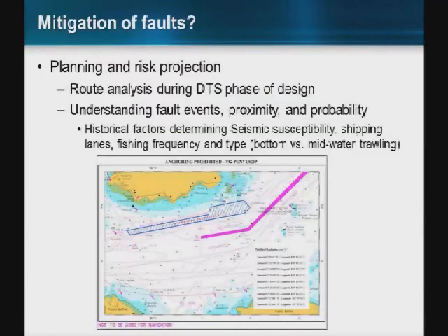So a lot of subsea cable investors and operators do a significant amount of research in terms of planning and risk projection. During the route analysis phase of the desktop study of the design, they do look at cable faults, proximity, probability, seismically active regions, and what type of fishing and shipping activity may cause further outages. But obviously you can't protect the entire sea. There are certain routes that you have to use just because of geography.